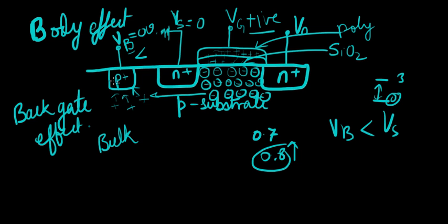So that's about it on the body effect. It is generally an undesirable effect, because obviously you're going to have to spend more to get the same current. So you have to try to find solutions to how you can decrease that. Of course, we'll discuss that later, but for now you just have to understand that the threshold voltage is increased because of changes in the bulk voltage.